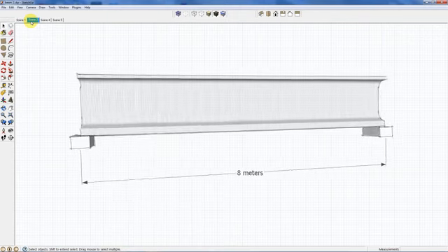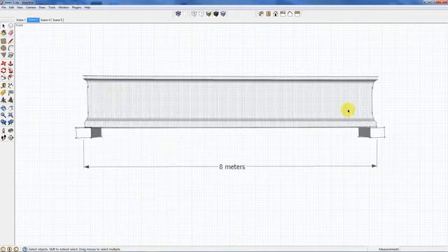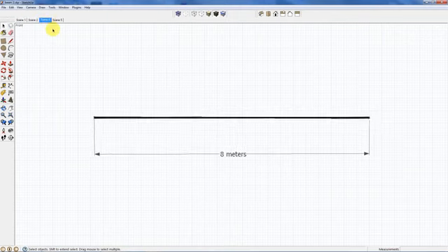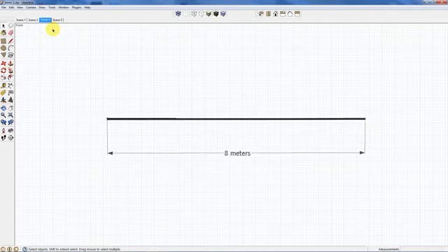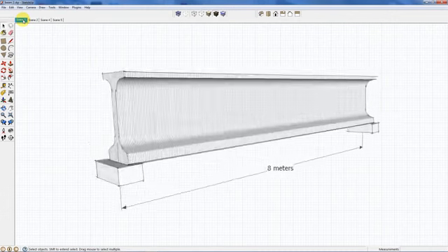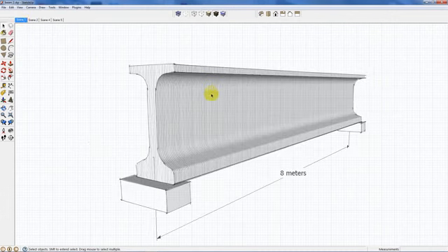It's got dead load, meaning it's got weight. This is how we represent it when we do our structural analysis. Now you can see there's quite a bit of difference between a line and the actual beam. Usually we put the line through the centroid, and I don't know where the centroid on this beam is. I'd have to figure it out. But the line represents the beam in our calculations. So we'll go back to that.